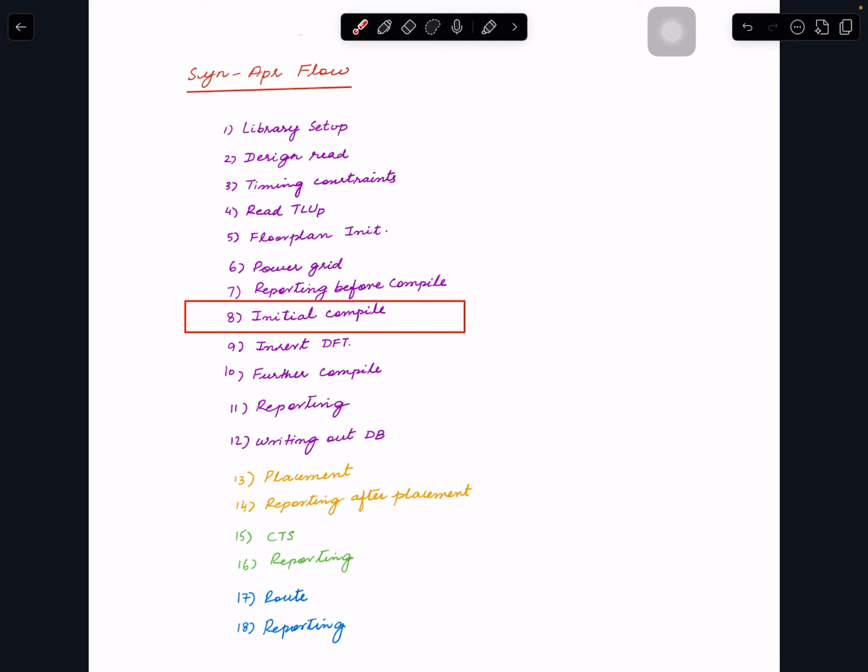In most of hierarchical physical design, if you are on a block, you will get those constraints from the top level floor plan person or design planning person. But in this example, I will be initializing that area. So just think that the block I'm taking, the counter, is your top level, and it is kind of flat. It's more a flat approach that we're adopting.